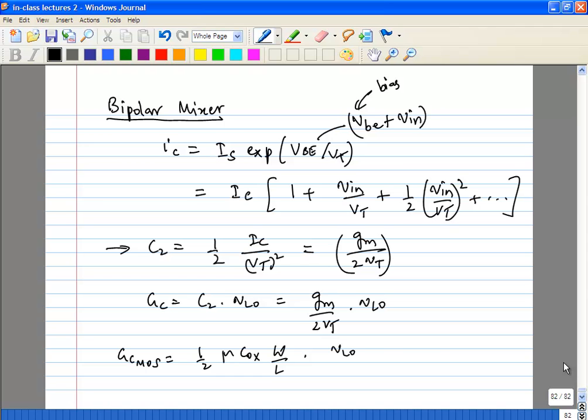For a BJT, is it possible to bias VBE? Why not? Voltage biasing of a BJT is very interactive. Basically, you need to do current biasing, but it will have a certain VBE across it. Here I didn't even say what this VBE is. It will be biased based on current, and it will have a certain VBE. You cannot even modulate VBE by giving a